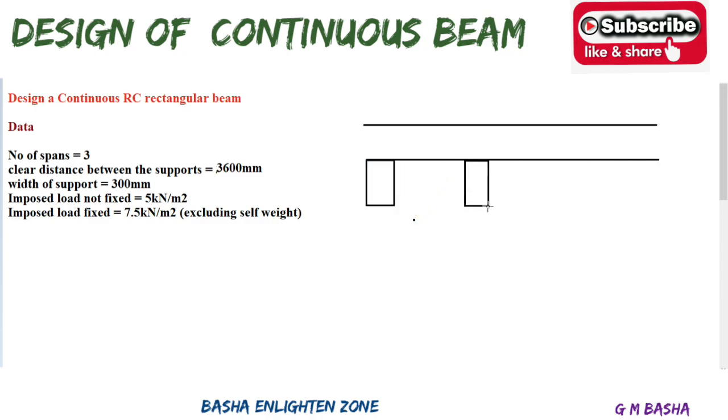So these are the width of the supports. I will just show a rough diagram. Number of spans will be 3. What is the given data here? Number of spans: first span, second span, third span. This is the span which we are designing here, and the clear distance between the supports is 3600 mm, and the width of the supports is 300 mm. Similarly this one also 300 mm, 300 mm, 3600 mm. So this is the given data.